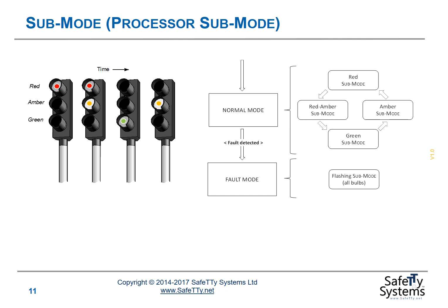So while the system is operating normally, these are the valid submodes. These are the valid light configurations that we can expect from our traffic lights. If a fault is detected, we're assuming there's only one valid submode here, and that in that submode, all of the traffic lights will flash simultaneously to indicate that something is amiss with the system.